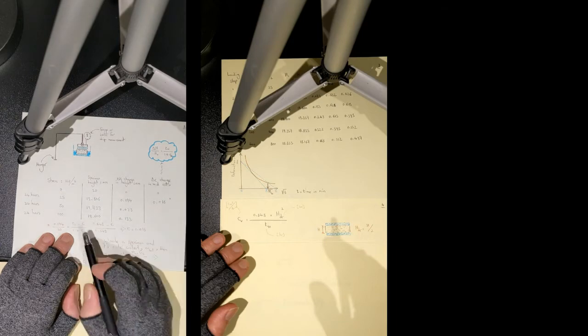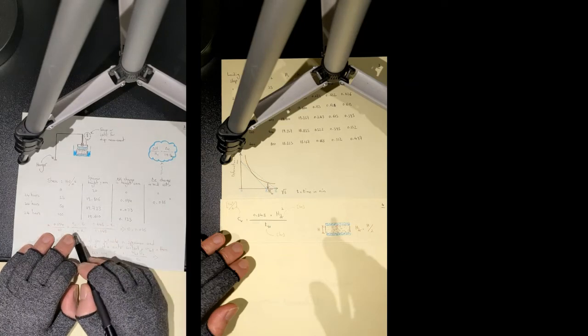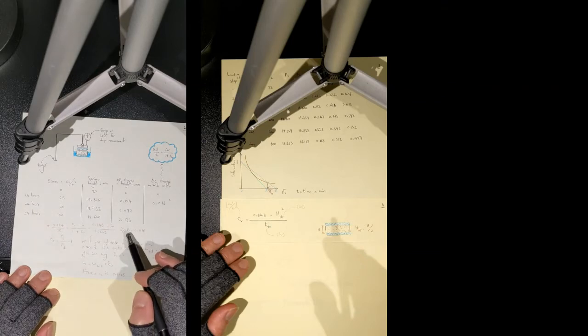So that's why delta e is translated into e naught minus e, divided by 1 plus e naught. Now e naught is known. Let's assume that your e naught is 0.648. Then 1 plus e naught is 1.648, and e naught minus e is 0.648 minus e. Everything is known with the exception of e, so you can determine e. e is your secondary void ratio.